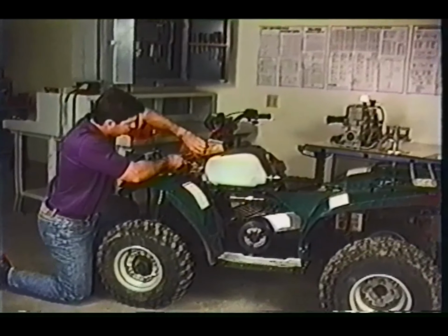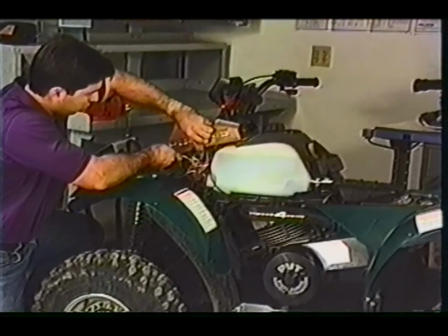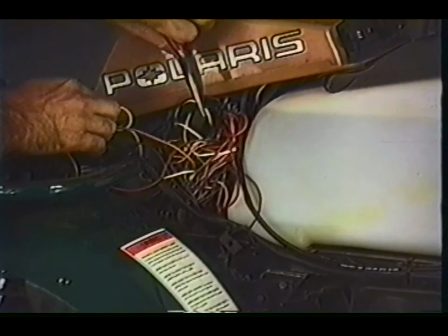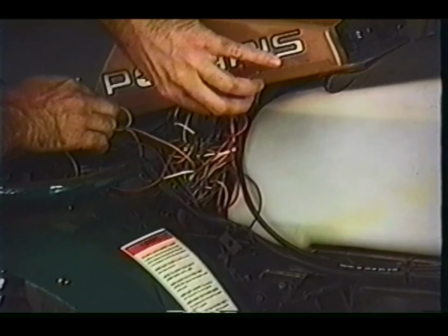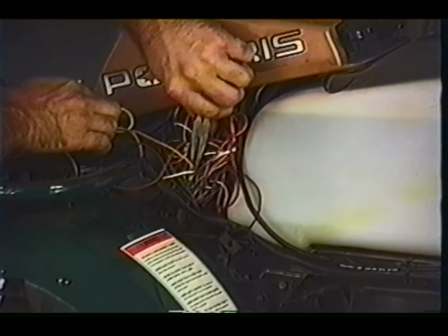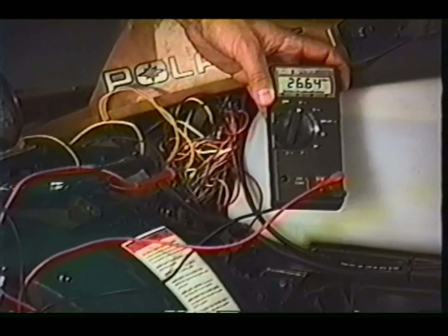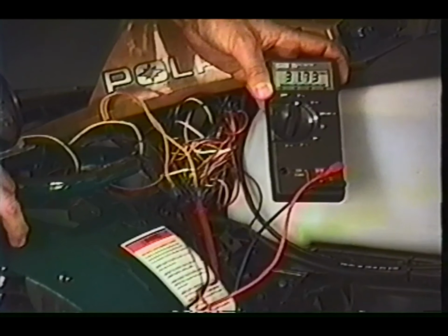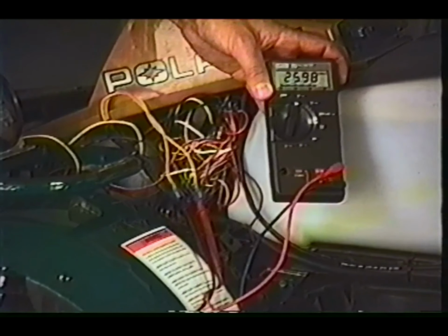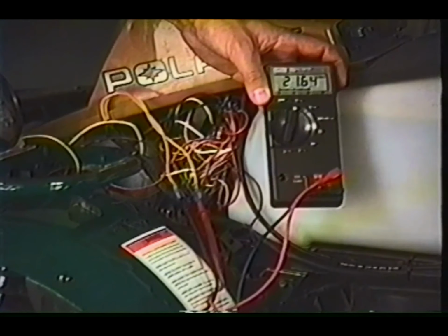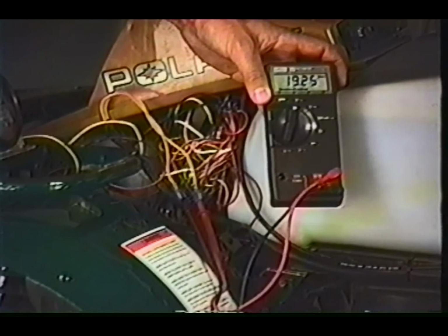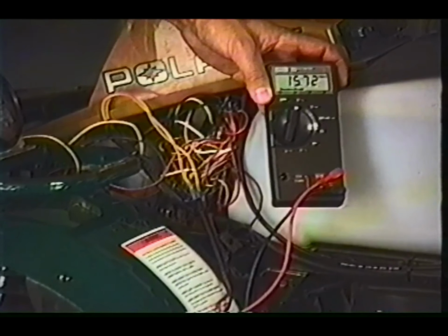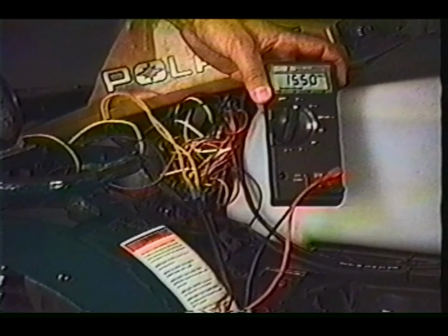In order to perform these tests, the alternator output wires must be isolated from the rest of the system. On ATVs with a 150-watt alternator, like this 300 4x4, it would be the yellow and yellow with red wires. Disconnect these wires from the panel and connect them to your Fluke meter leads. For the voltage test, make sure the red lead is in the volts outlet of the meter. Turn the selector dial to the AC volts position. Start and increase the engine RPM. Voltage should be above 20 volts at 3000 RPM.